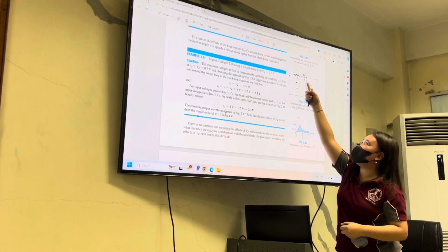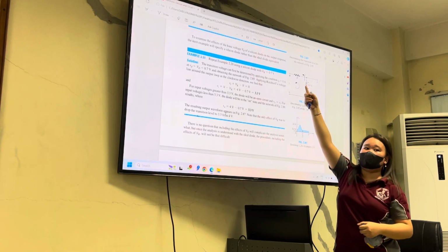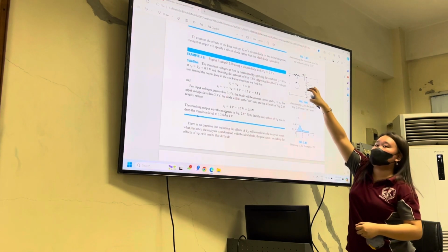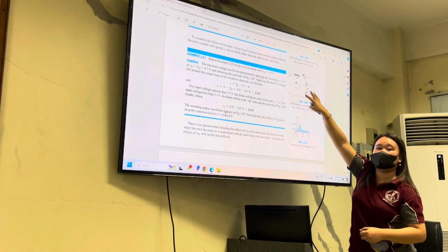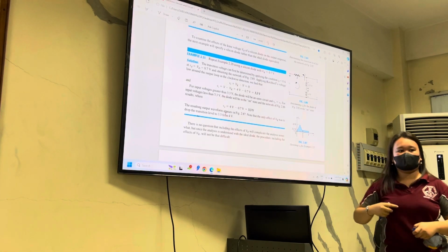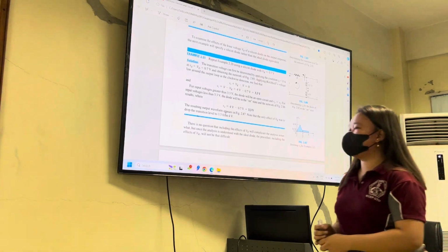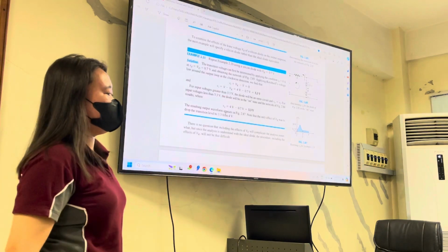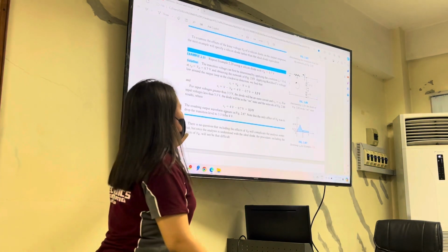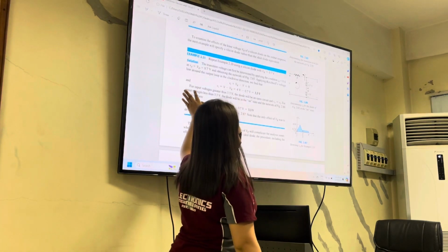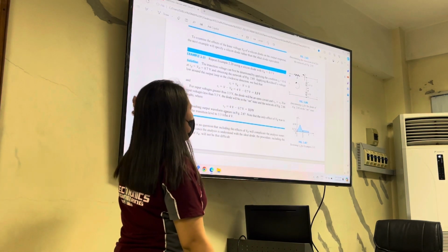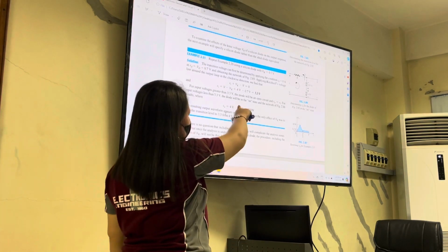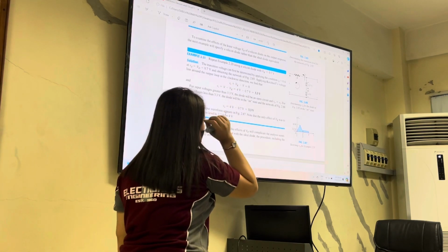For example, this is positive, negative, positive, negative. If the diode is reversed, it is series aiding. This one is opposing, so you subtract. But I don't rely on that; I always make a loop. So for the on state, we make a loop. So V input, plus 0.7.